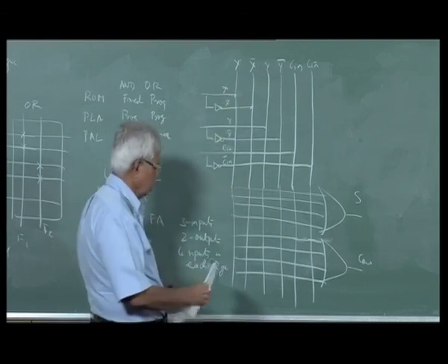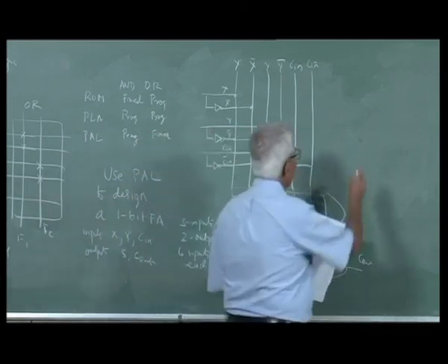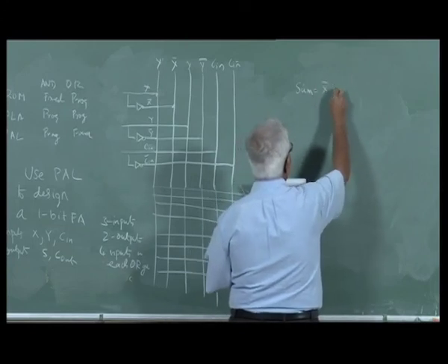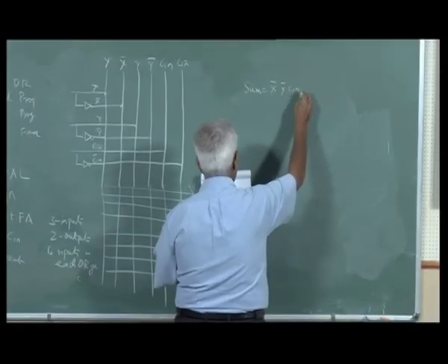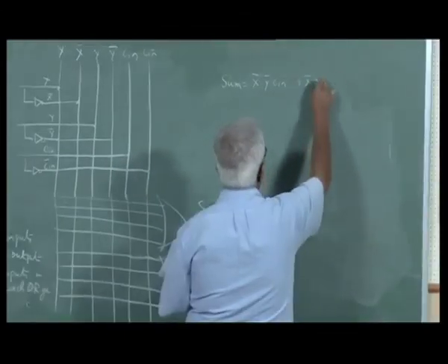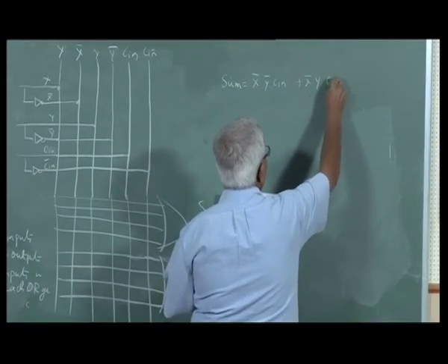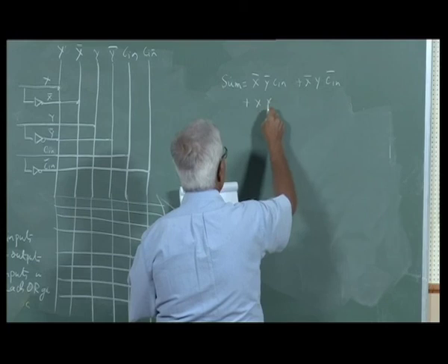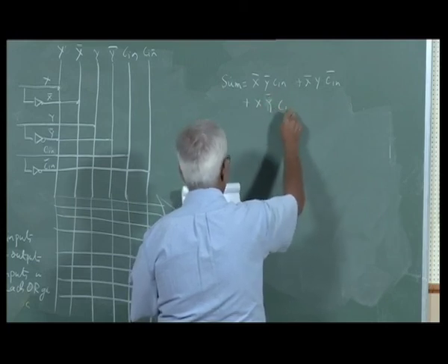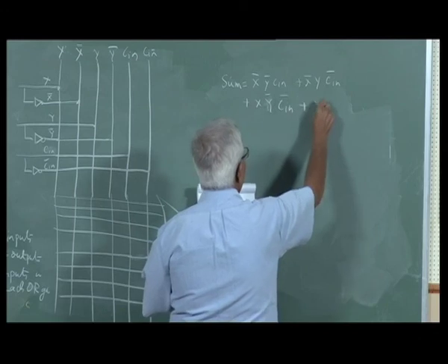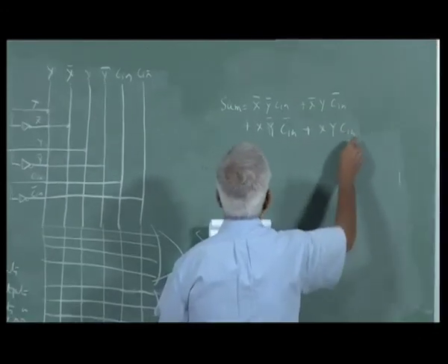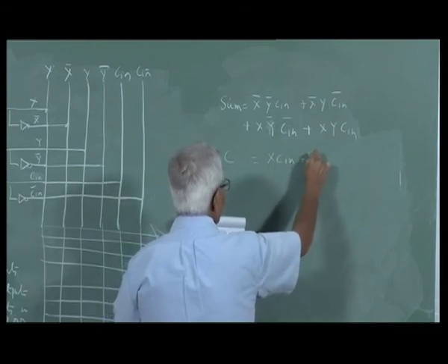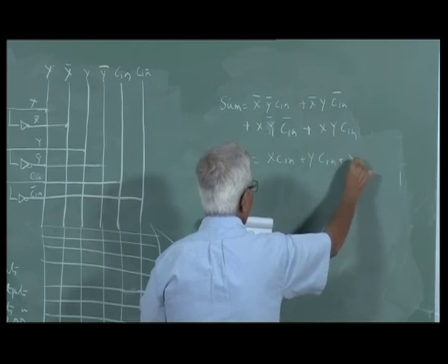For example, if you write the sum expression: x bar y bar C in, x bar y C in bar, x y bar C in bar, x y C in. Carry is x C in plus y C in plus xy.